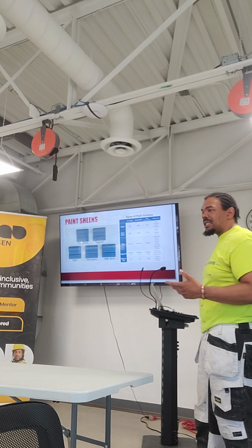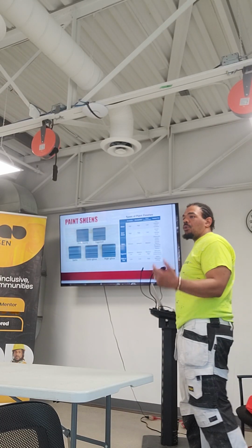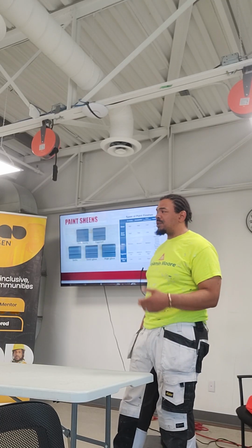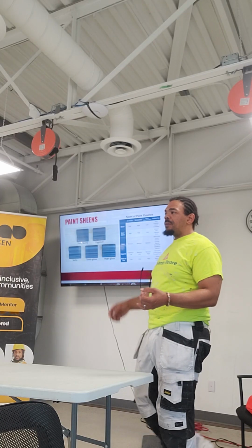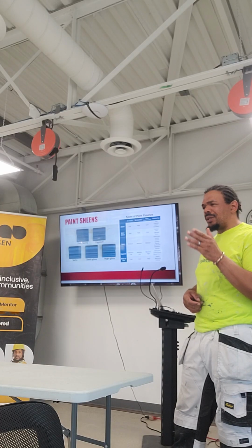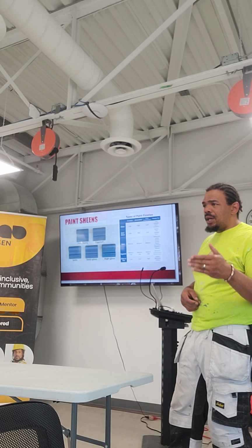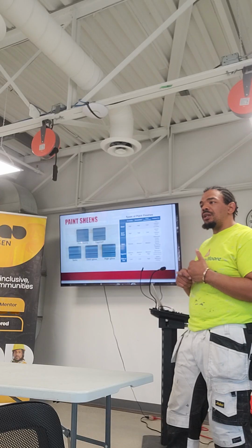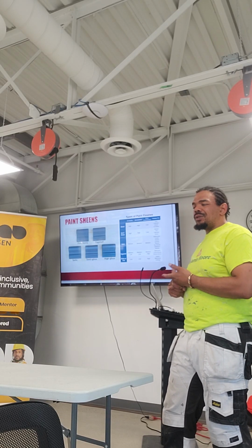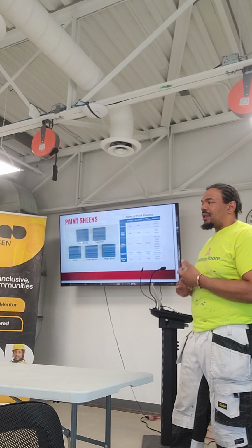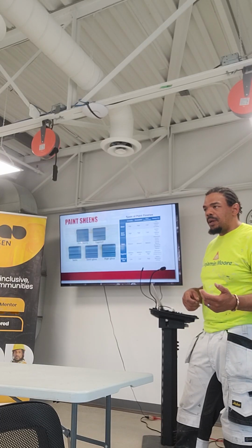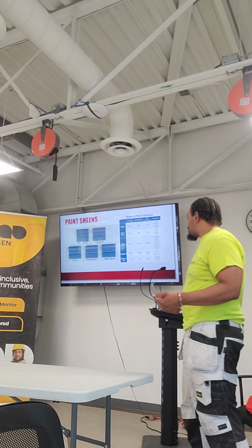So then you have your eggshell. This is reserved primarily for a lot of walls. Occasionally people will put eggshell on doors and frames, but it's primarily reserved for walls because it has a limited sheen factor. So the walls are shiny, but not too shiny. They're not too flat. So they have some sheen, and with sheen comes some durability. So the eggshell paints are a lot easier to wash and clean. They're a lot easier to scrub afterwards and remove dirt and stains from, as opposed to repainting over them.